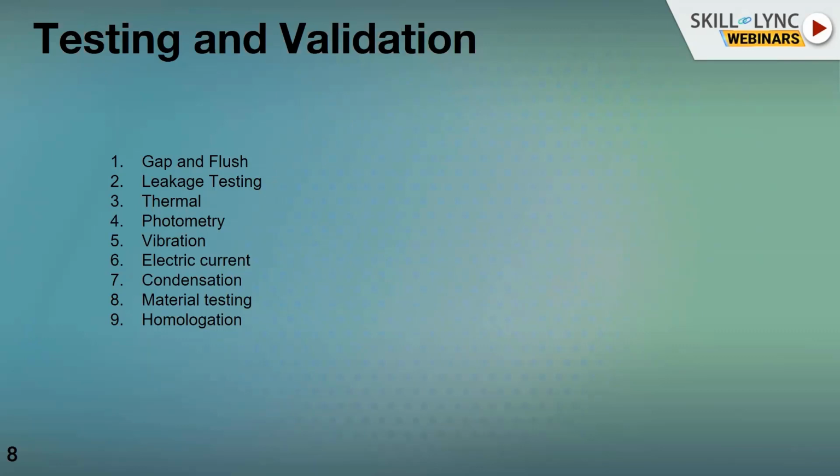So that type of requirement, this photometry can check, and it will give you an idea. With the simulation also, you can check how much output is coming in your lamp, and accordingly you can modify your optics, you can modify your light source, or if you're in the LED case, you can change the binning also. So this is how the photometry validation is compulsory.